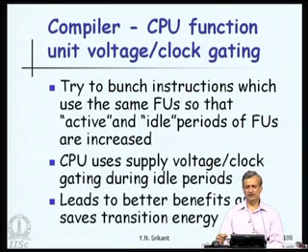The instruction scheduler brought them together. So, the ALU now keeps itself busy as long as possible, that is as long as there is no dependency on the next instruction and it is forced to wait. So, assuming that there was an idle period between consecutive 2 instructions, now there will be no idle period between these 2 instructions.